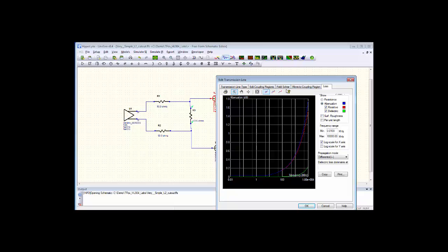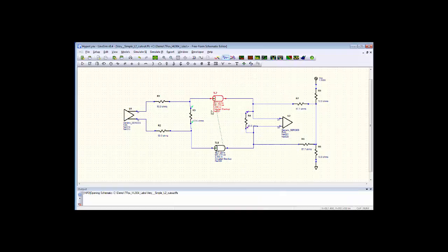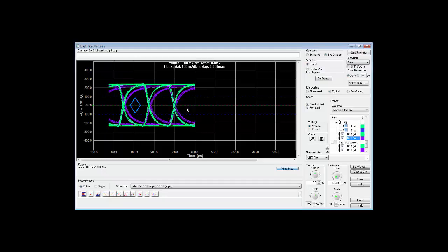But anyway, go through, work with those things, and just get some idea of how this all goes together, because you can't go through using some brain-dead idea that since it's a 100 ohm differential, you use a 100 ohm resistor here. A 100 ohm resistor may or may not be the right number. The point is, what does the signal look like when you're going into your receiver? So work with those things, and that is it for this part.